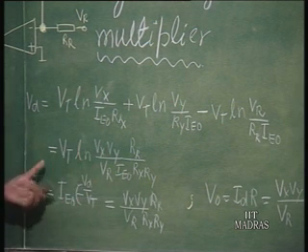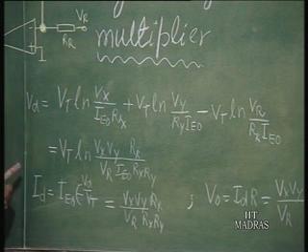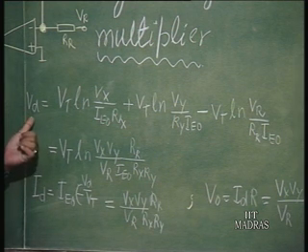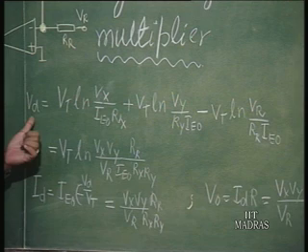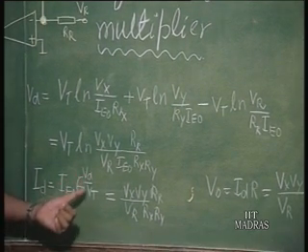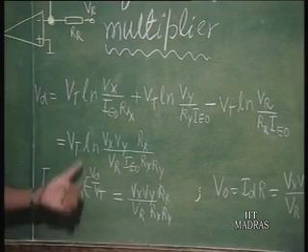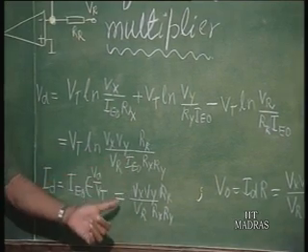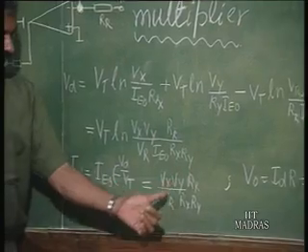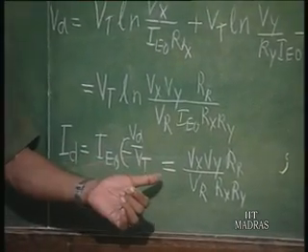So, that is the voltage that you develop, and if that voltage becomes the forward biasing voltage of another diode, then you take an antilog of that voltage, that means that will be I e naught exponent V diode divided by V t. So, this V t gets cancelled, it is exponent log of this value, which is that value itself, V x V y by V r, R x R y R r, I e naught getting cancelled.